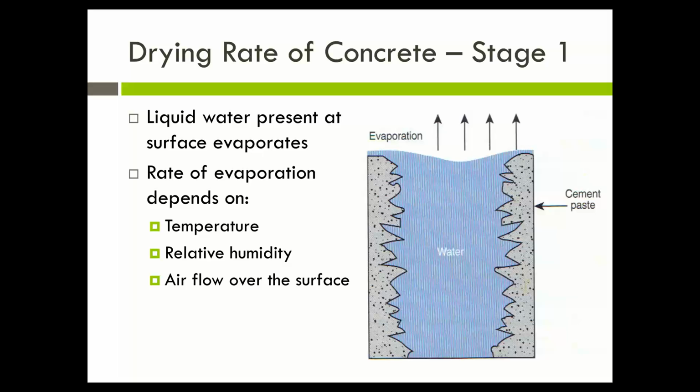And we should know that so long as the concrete is exposed to the environment, it is possible, and in fact foreseeable, that drying is going to take place. Drying, in the first stage, refers to the water that is lost from the surface. And it's lost by evaporation, no different than if you were to put out a bowl of water in a room that's not at 100% relative humidity, the water would evaporate and go into the air until all of the water was gone.